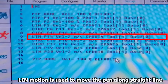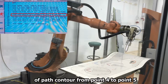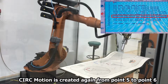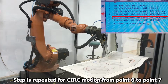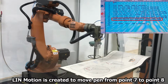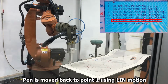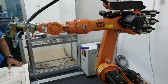Then, LIN motion is created to move the pen along the straight line of path contour from point 4 to point 5. After that, CIRC motion is created again from point 5 to point 6 to move the pen on the return path of the contour. The step is repeated for another CIRC motion from point 6 to point 7. Once the pen is perpendicular to the flat work table, a LIN motion is created to move the pen from point 7 to point 8. Finally, the pen is moved back to point 1 by using LIN motion. The robot is then back to home position.